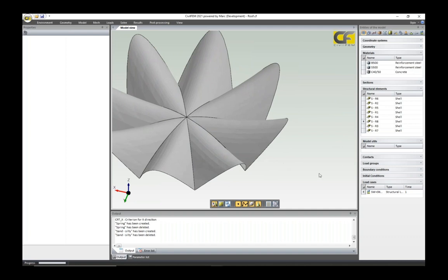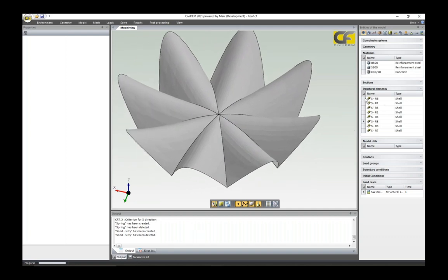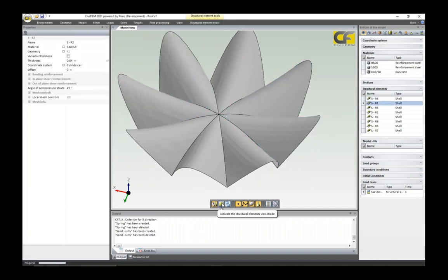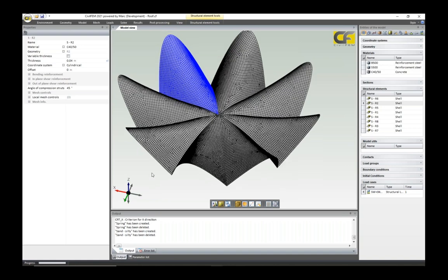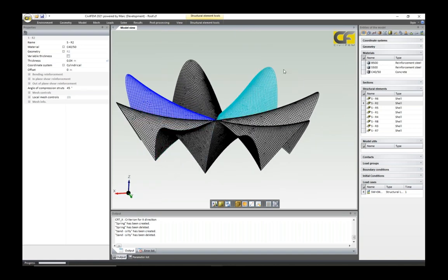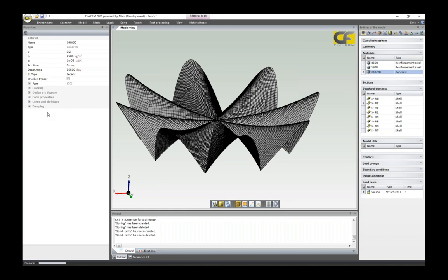And then we have meshed with shell elements for different parts of this, and each of these shell elements has a thickness of only 4 centimeters, so it's very slender. The concrete we have used is C40/50, and as I said before, we have set 2 different behaviors, one for nonlinear analysis for the solution level. CivilFEM already had this, and you can find different webinars where we explain a lot about that.